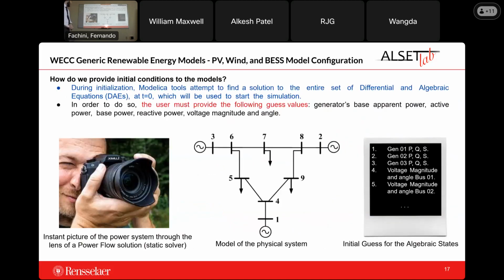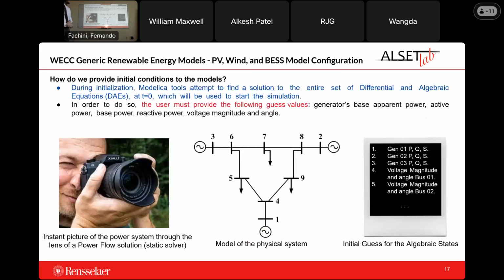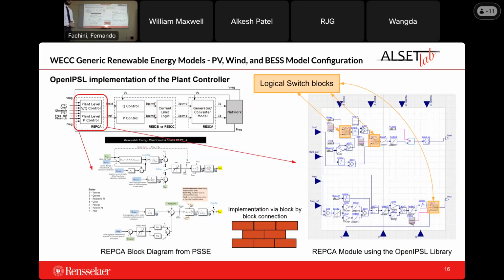Okay. So the implementation process of the models, as such, is it correct that it's only block connections? No. The majority of it is block connections, but there's also equations behind on the model. Yeah, because you need to map it to the terminals. When I'm doing it now, that I have to actually do it myself, you have to match the PF component. You have to read the power flow data for initialization and so on. So the dynamics of the model is built through a component-based connection, but the initialization process under the hood is done on the equation section.